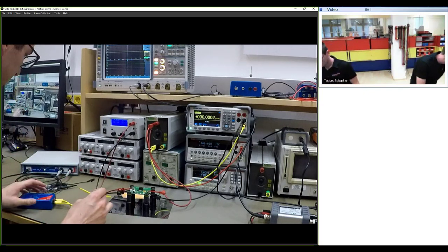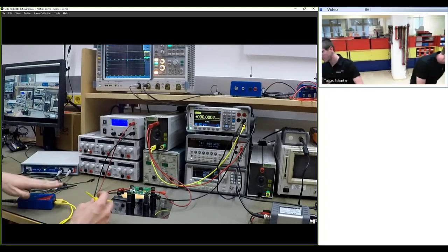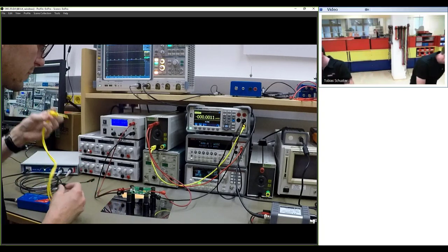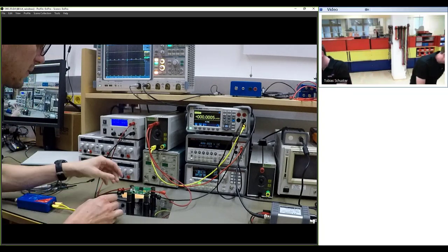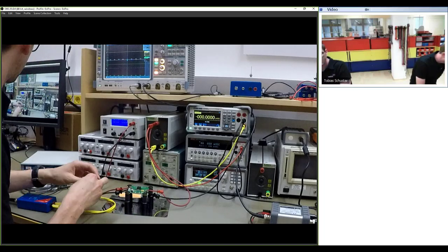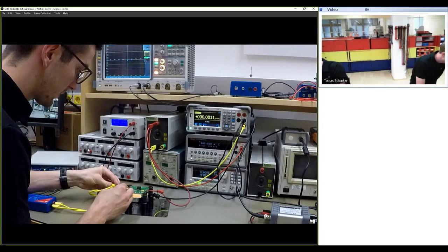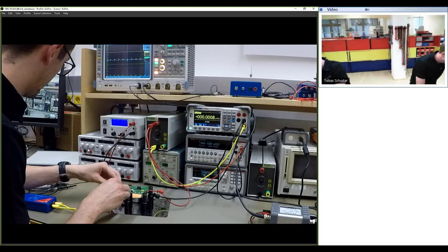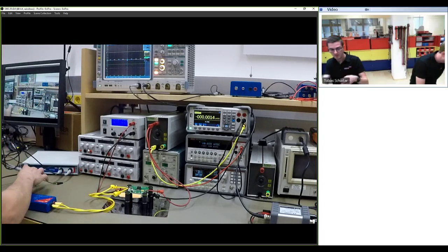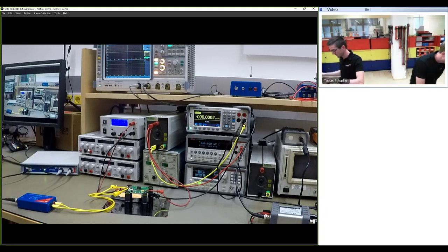So now I connect the injection signal from the output of the Bode to the injection point. We already have soldered the resistor and 2 pins on it so that we can connect it easily. First connect the output, that's the disturbance signal. Then I use the probes.